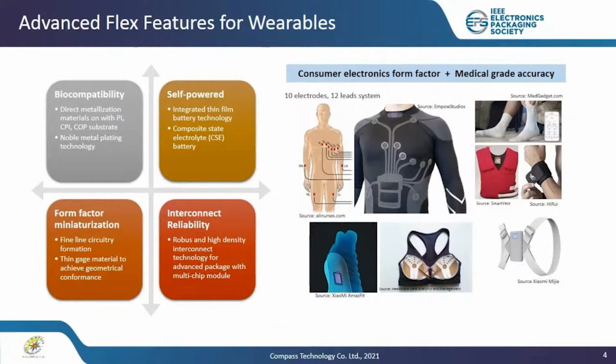For form factor miniaturization, the device needs to provide economic benefit to the user without limiting the number of ICs or sensors. This can be achieved by scaling down the circuit dimensions and using more flexible dielectric materials. Finally, higher functionality can also be achieved by low-volt high-density interconnect technologies, and that usually requires system-on-flex packaging.